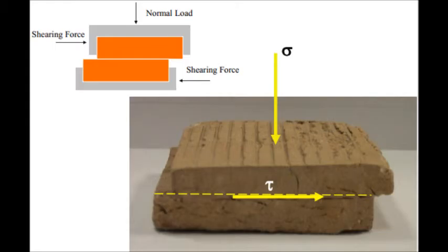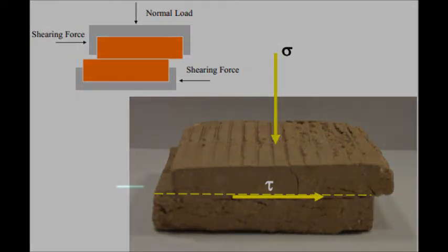And after recording, this is how the sample will look after doing the shear strength test. We have a normal stress and a shear stress, with the shear directed horizontally. Because the grid was perpendicular, that's why you have those lines above the used sample. And when you apply stress, the soil will be disturbed until it reaches failure.